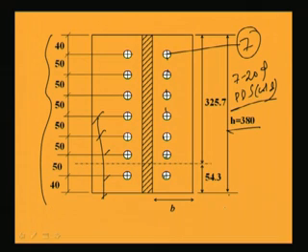So, this is all about the design of riveted joint. Riveted joint can be designed in this way. First, we have to see whether the load is lying in the plane of the riveted joint or perpendicular to that. On that basis we have to decide, and again if it is perpendicular to the riveted joint, then whether it is cold rivet or hot rivet. So, on that basis we have to design.